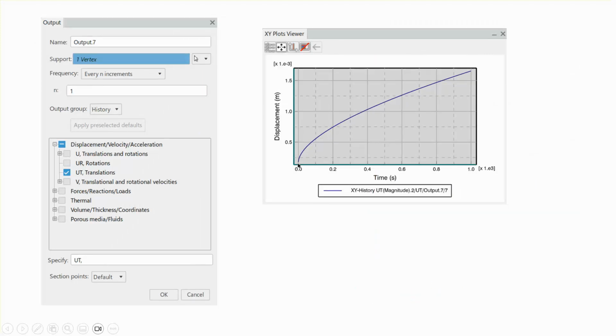Notice that I can plot the displacement at the very right hand side of the sample where the load is applied as a function of time. And you can see that as time goes on, after 1,000 seconds, that deformation goes from roughly 0.18, something like that, millimeter to 1 point something, 1.6 millimeter, I believe. These are in meters, by the way. But anyway, it shows you the concept of creep.